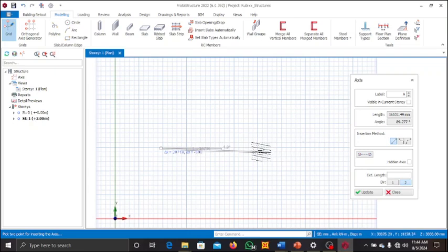Right? You can press the F2 button on your keyboard, and that is going to help you input the length of your grid manually. We can decide that the length of our grid is, let's say, 30,000 millimeters, because remember, when we're checking our units, length on your windows is always in millimeters.